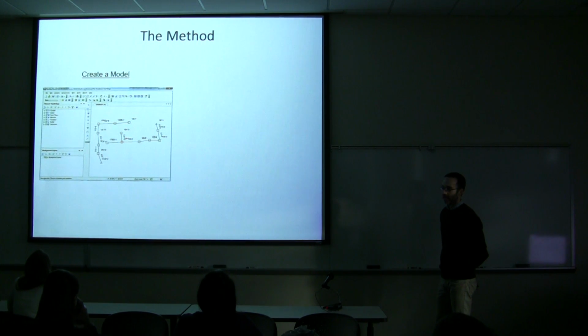And so StormCAD allows you to assign a contributing area that flows into a catch basin, and through simulating a storm and adding the flows that would already be there from wastewater, compare the capacity of the pipe, how much water potentially it can handle, to how much water would be there during a certain wet weather event, maybe a 2-year storm or a 5-year storm or a 10-year storm.